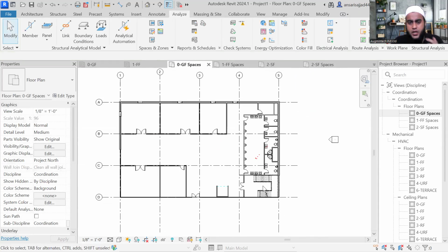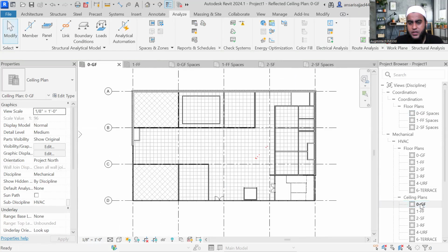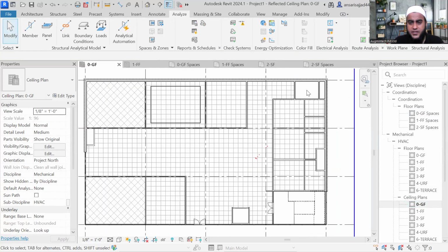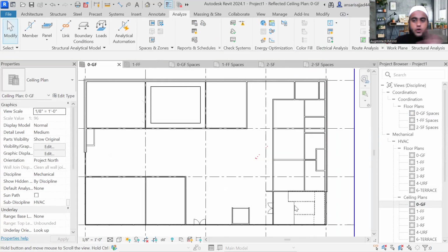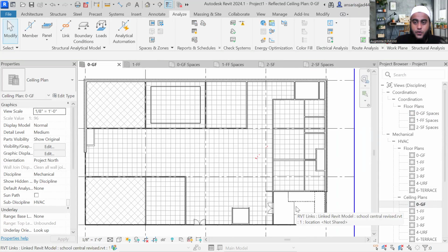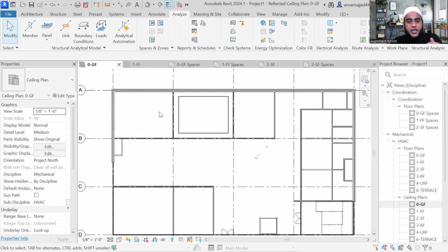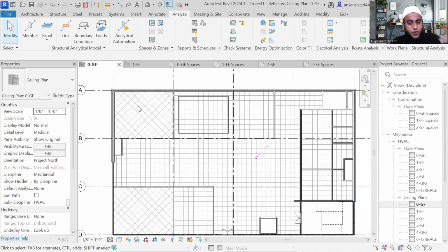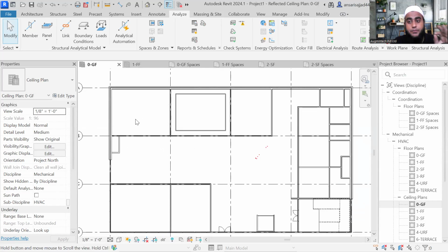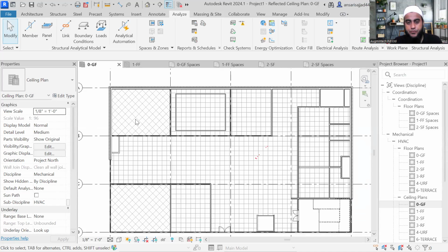I will explain it to you. You can see in the ceiling plan. When you open the ground floor ceiling plan, can you see? Here in this room, this is our electrical room. Here we do not have any false ceiling. In the staircase also, we do not have one. So for any room where we do not have a false ceiling, you have to consider the height up to slab level when you are creating these spaces. Otherwise, if there is a false ceiling in any room, for that you have to select the maximum ceiling height. Is it clear? Tell me, please, all of you.